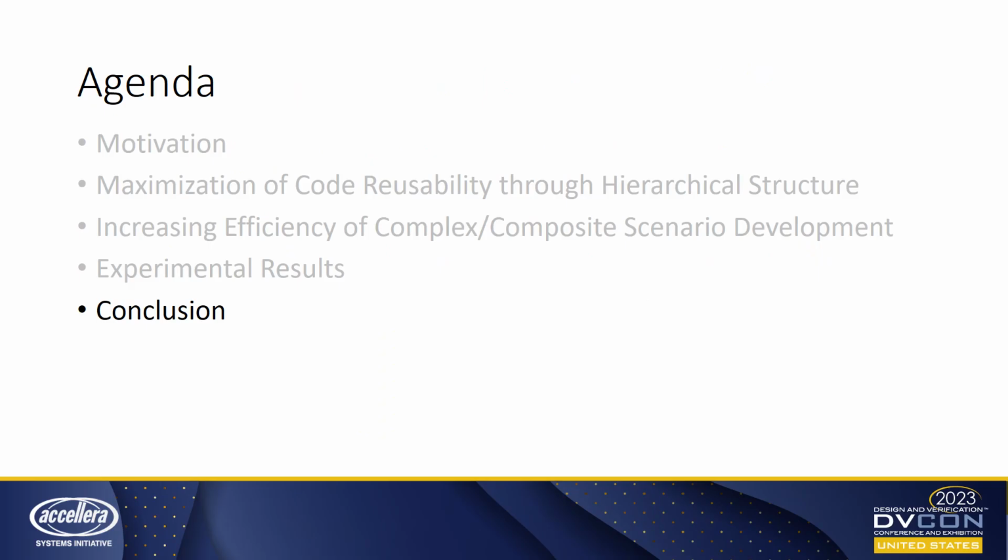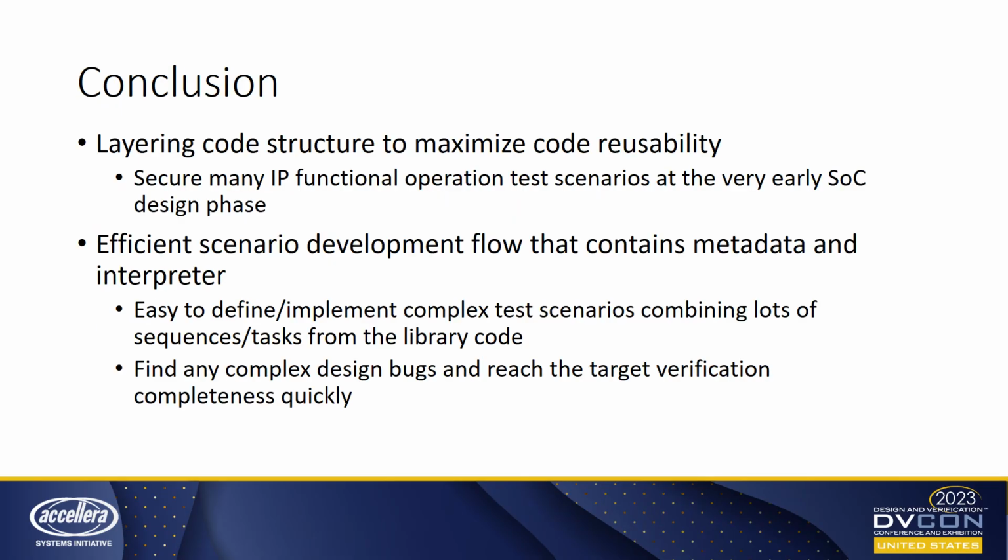Now, I'm going to show you the conclusion. In this presentation, I propose a layered UVM code structure and an automatic test scenario generation framework based on metadata and an interpreter. Our results proved that many test scenarios can be secured at the very early stage of SoC design by using reusability.